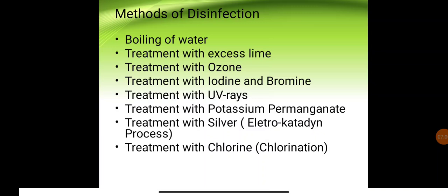Ozone inactivates the microorganisms by two methods. One is by direct oxidation only, it inactivates the microorganisms. The other is decomposition into hydroxyl radicals, which are very strong reactants.